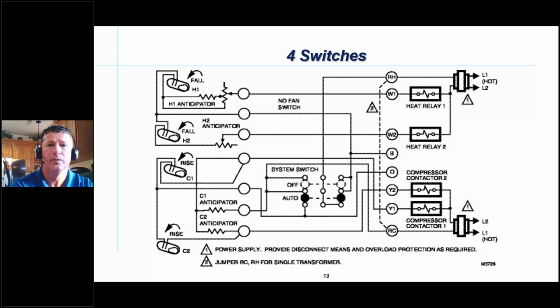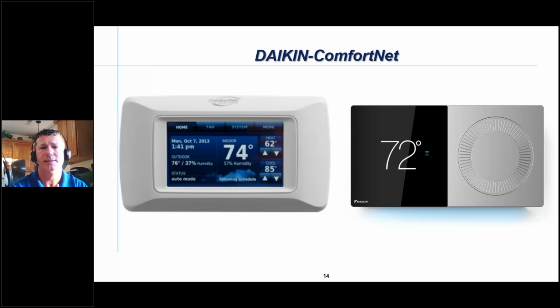So we started getting into digital thermostats, and different types of thermostats, and particularly as our equipment is progressing, we're getting into modulating control. We're getting into equipment that's going to need modulation of its signal. It's going to need its switches to not only be just an open-closed switch, it's going to need to be something that can have variable control, because we're going to start using variable voltages to do that. So as we moved into communicating equipment, we started altering our thermostats pretty drastically.